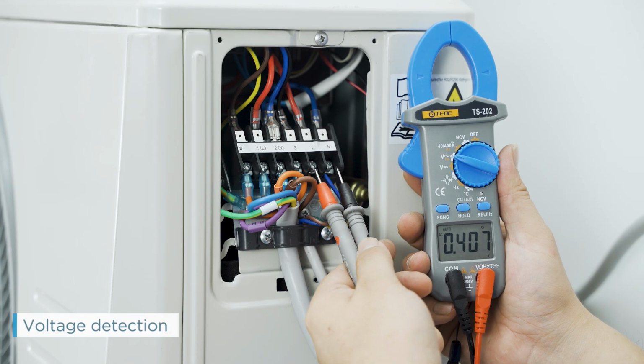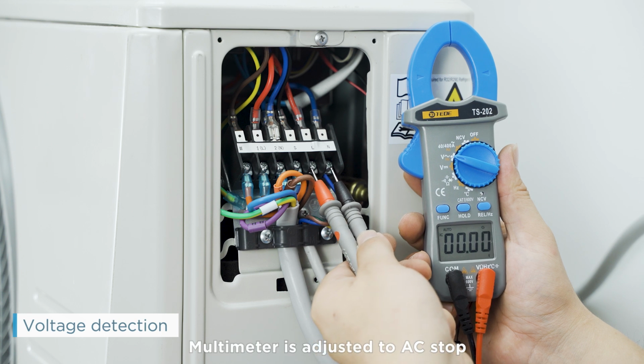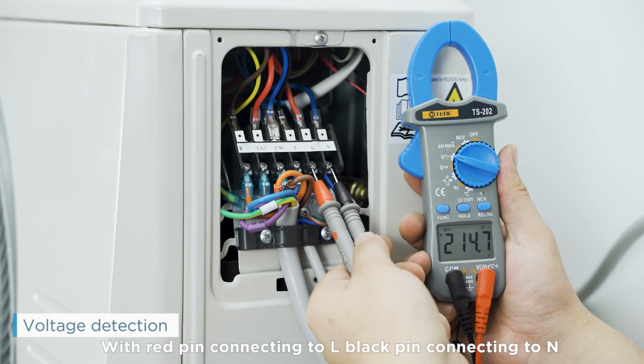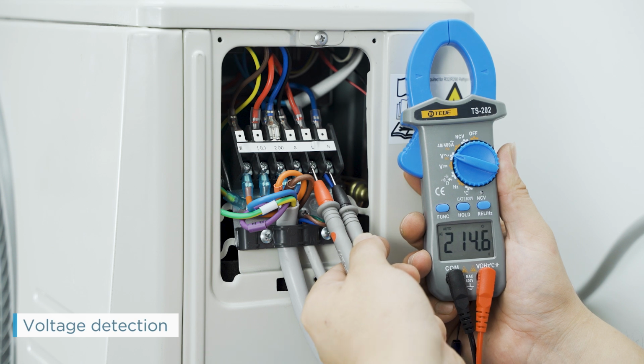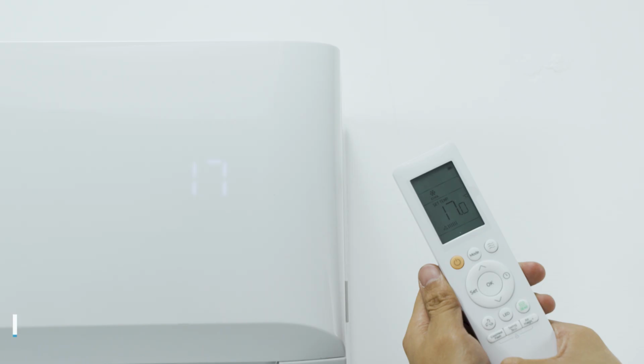Voltage detection. The multimeter is adjusted to AC stop. With the red pin connecting to L and the black pin connecting to N, measure whether the running voltage meets the range of use of the product when the air conditioner operates. Note, you can also use the remote control RG10 to enter engineering mode for voltage check.